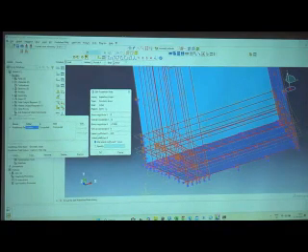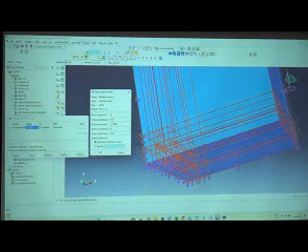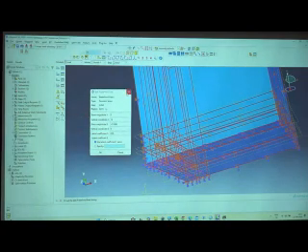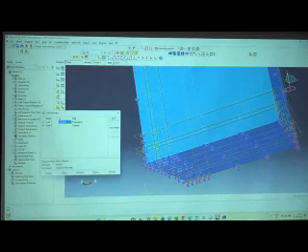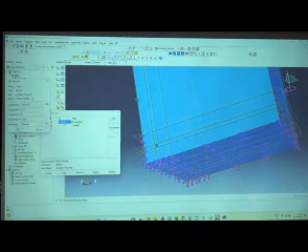We assume that the lateral coefficient is the same, so I only took the lateral coefficient of 0.65, and 12 here is the height, the depth of the soil domain. After this, I applied the gravity load. The gravity load is minus 9.81.